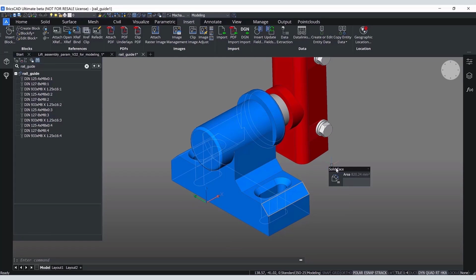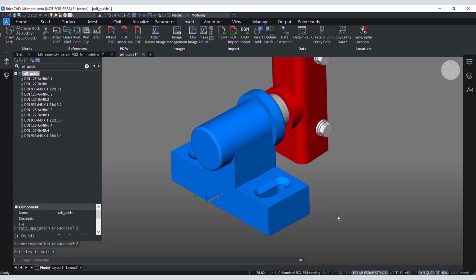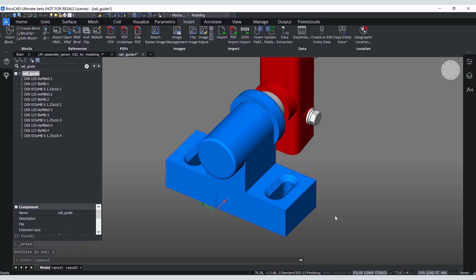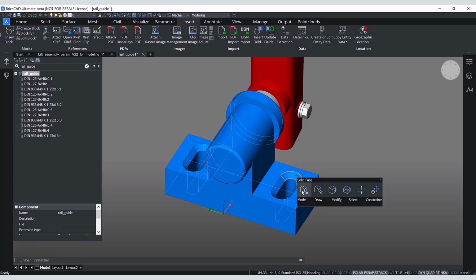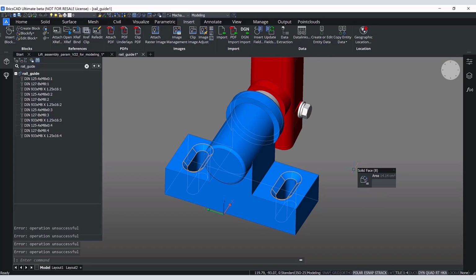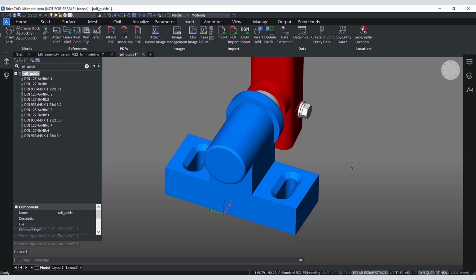How can we do this? Of course, we can always just manually select the required faces, but now we have a faster way. As you saw, we use a new tool which allows us to select chamfers with the same offsets. It is part of the very powerful dmSelect command, and if you want to feel the full power of this command, you need to call it directly. It allows you to select faces and edges by attributes like area, length, and a lot of other possibilities.